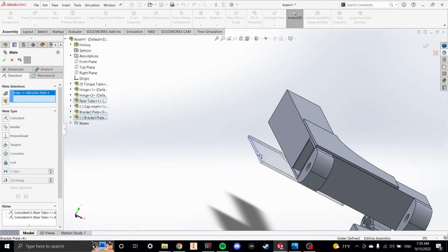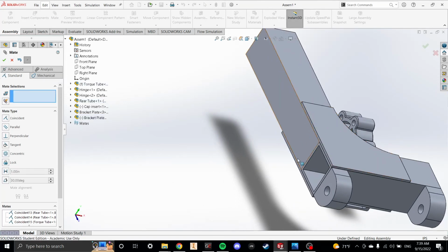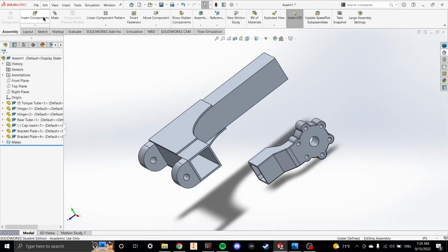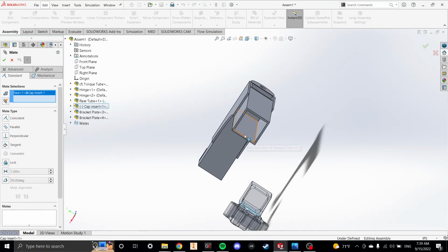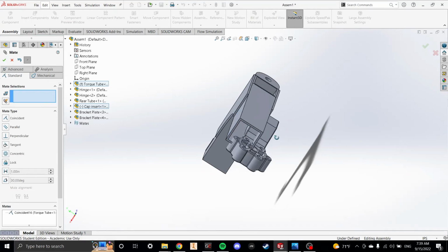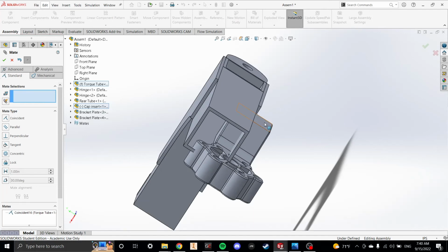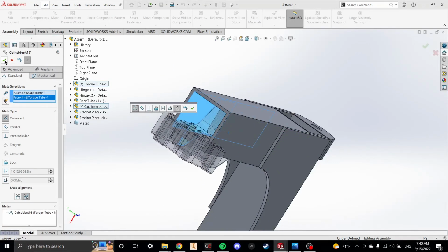Once we get this locked in place here, both sides are good. So everything is connected, non-moving, grounded. All that's left to do is just insert this piece. So this is also quite simple. We're going to do a tangential constraint because we know the outside diameter of this tube matches the inside diameter of this tube. Having a surface-to-surface constraint will work for our purposes and allow us to move it.